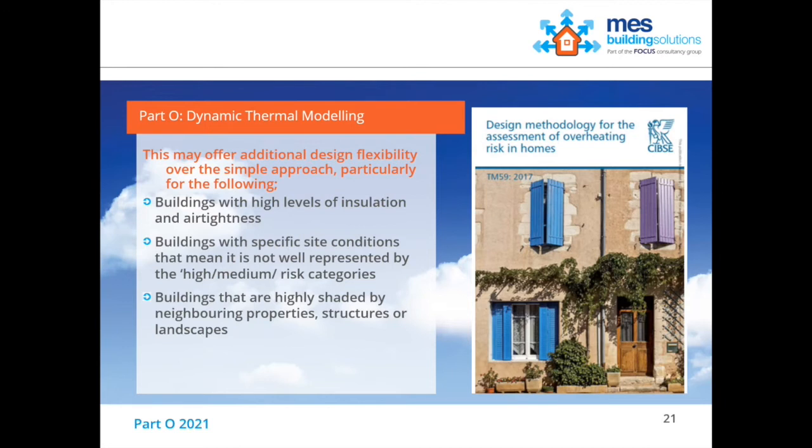It's not necessarily going to work for all schemes. If we're looking at buildings which are incredibly airtight and incredibly well insulated, then the simplified approach may not be applicable. We can't open windows. If we have site conditions where the planners or environmental health said it's going to be far too noisy, then to mitigate that noise risk from a particular source, all those windows on that facade will have to be non-openable. Then again, we can't use the simplified approach because we can't open the windows.